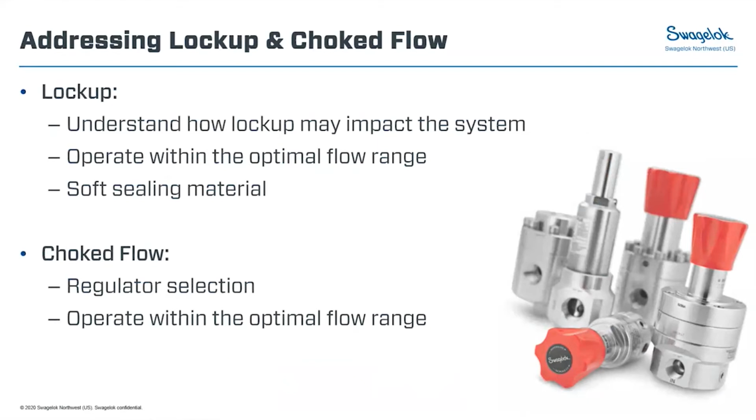Real quick, we had a question with regard to lockup. Does this mean that we need to use a relief valve downstream of the regulator? Yeah, great question. I hate to use the term always, but we pretty much always recommend installing a relief valve downstream of the regulator.